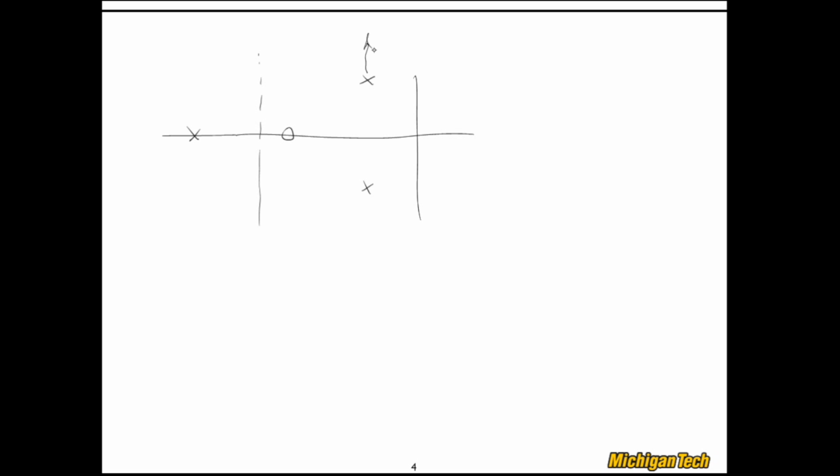So instead of the root locus going up like so, I'll cross those off, it's going to go like that. Notice what this lets me do is I can increase omega n. Right? This is increasing omega n as the circles have larger and larger radii. But my zeta, which has to do with these lines, could be still kept relatively low as omega n is increasing. So an interesting design feature.